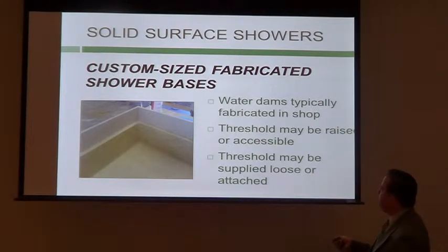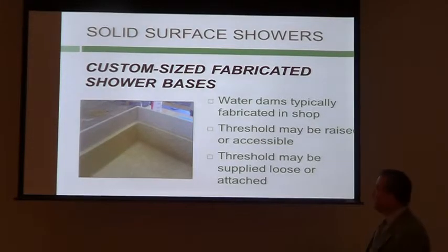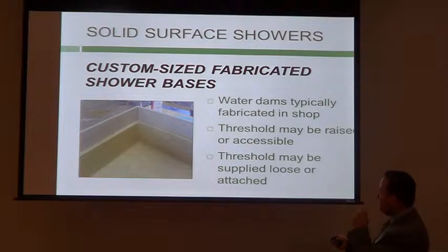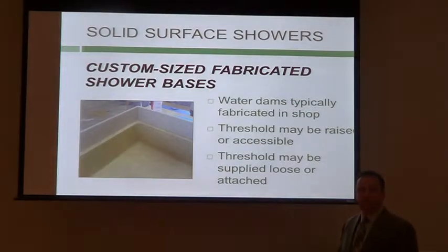Well, I just call it a 2-step water dam. So I've got my lower step to receive the finished wall product, and then I've got my second higher step to seal that joint. So this part here, you can see it's even a different color, right? Because it doesn't matter what color it is, it's completely buried behind your finished wall product, but it seals that joint right here where the finished wall product comes down and is seated on that inner lower step.